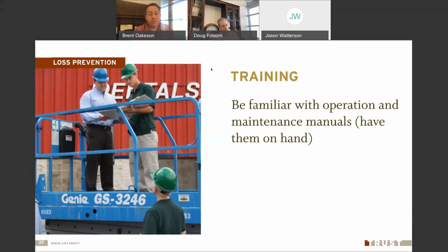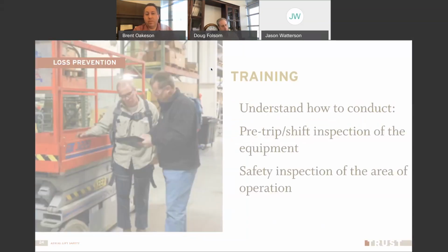If you happen to be renting a lift, that's one thing to check for. If the vendor brings you out a lift, ask them for the manual. Ask them where the instructions are. Have them show you and teach you what you need to know about those manufacturer requirements before you use that lift that you rent.